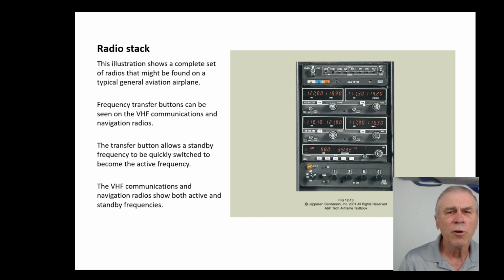And there are little buttons, these white buttons, that will switch what navigation frequencies you have in the active and the standby, and the COM arrow toggles you from what you're actually talking on now, 122, and what you're standing by to talk to somebody else on, 118.9. You have somebody on hold.